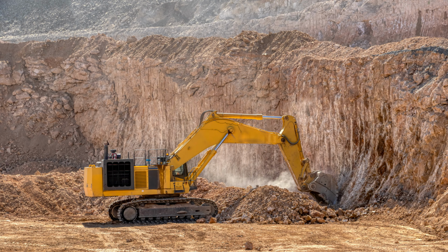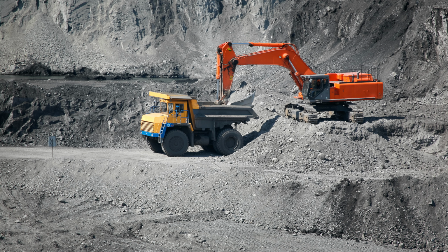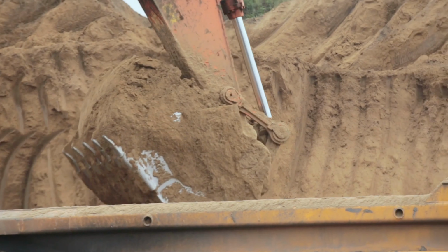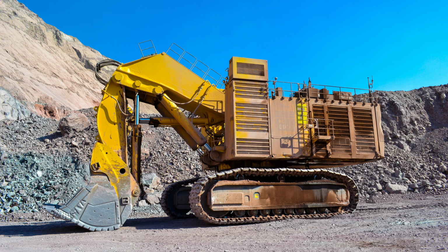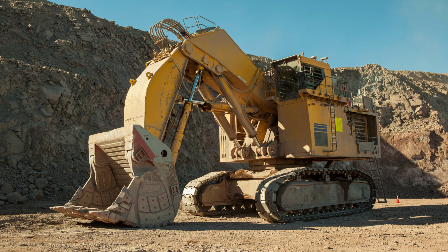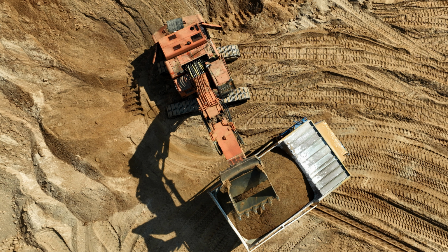Larger machines, such as 40-50-ton excavators, can generate 300 to 400 kN of digging force and are commonly used in quarrying or heavy earth moving. In extreme applications, like mining and rock excavation, very large excavators may produce more than 500 kN of bucket force, allowing them to break compacted rock layers and hard geological formations.